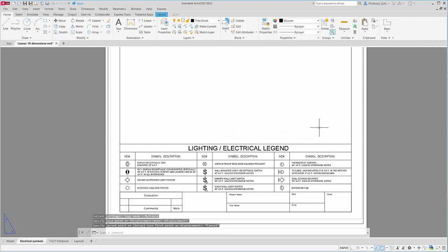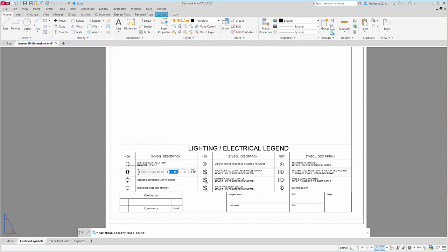It looks very professional. Now these symbols are going to be used on the drawing in order to create an electrical layout. The symbols that are drawn here are going to be copy and pasted into the main drawing and then scaled to the appropriate scale for continuity with the scale of the layout. So I will, in this case, select Edit, Copy with Base Point.